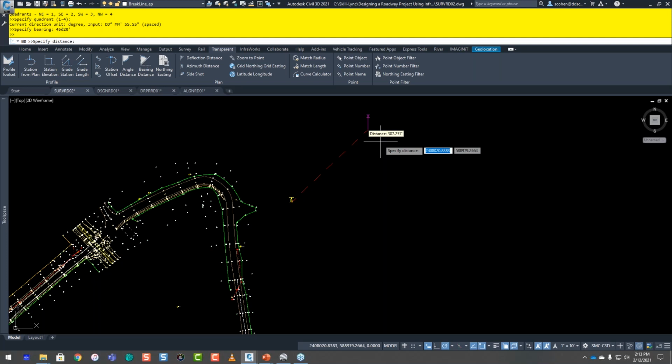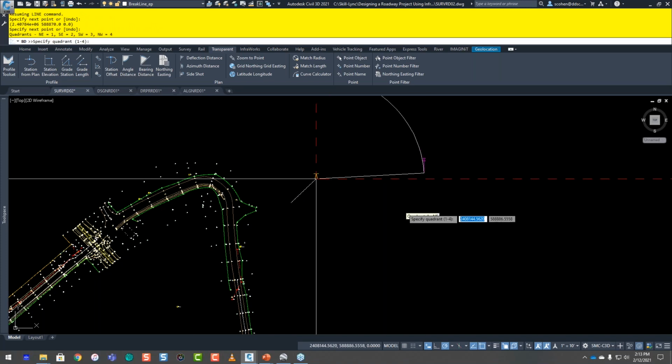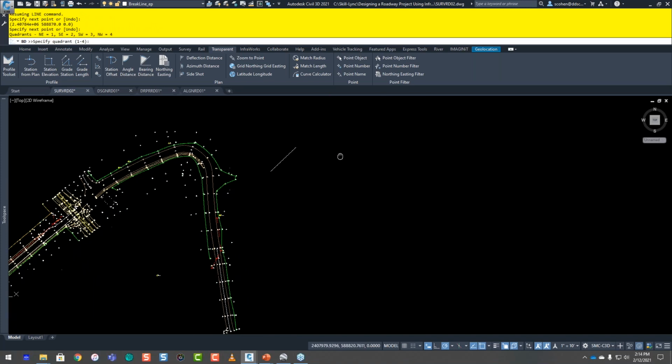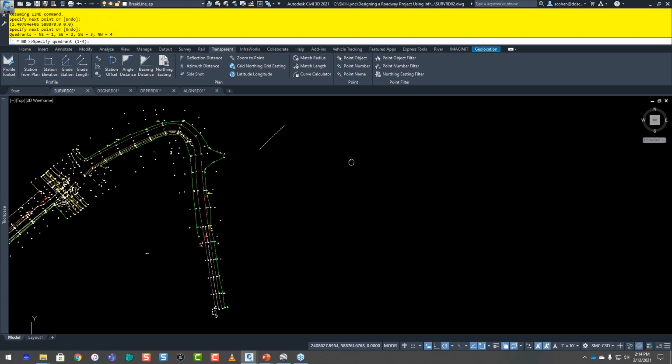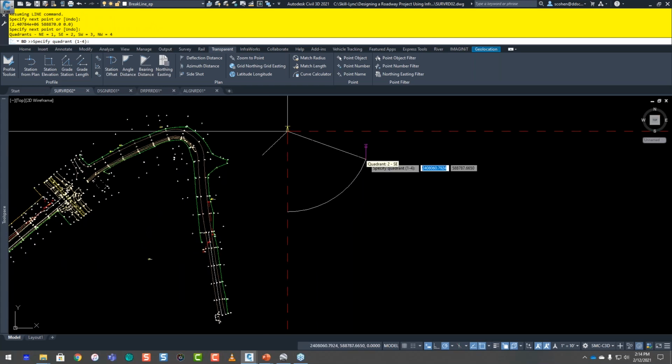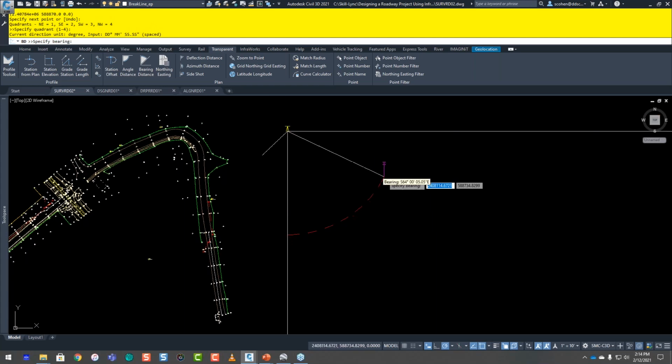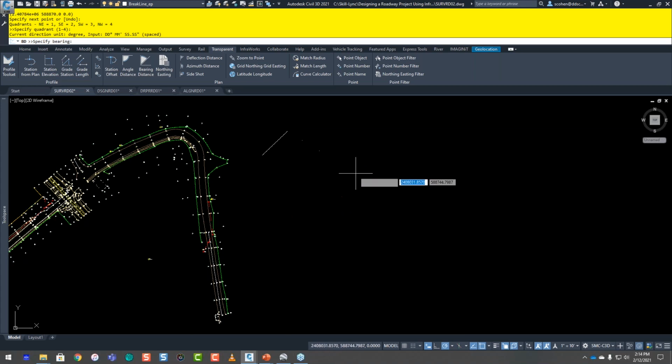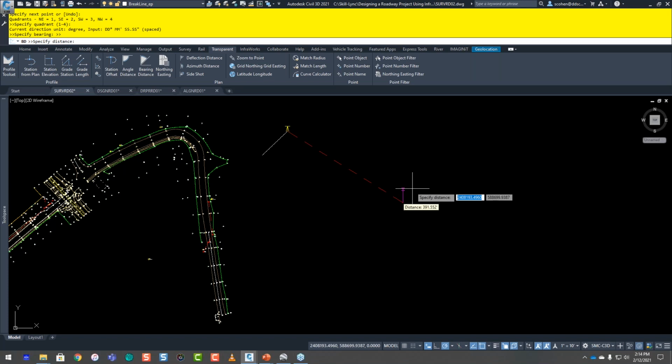All right, then of course you're typing a distance in here, so I'll type 100 feet, press enter, and now I can just keep going. That's the beauty of this functionality here, okay? And so now let's say in this direction here, I'm going to go with this direction, and my bearing, I'll just pick one arbitrarily here, and then I would type a distance in again. Now, what if I'm doing some parcel, and the sides of the parcel are exactly square, or they match another length within another parcel or a boundary somewhere.